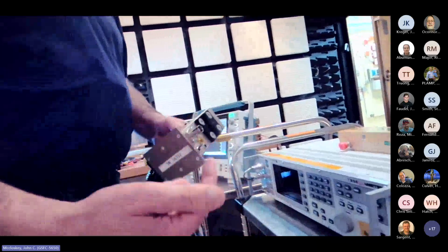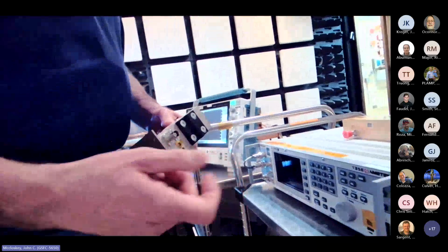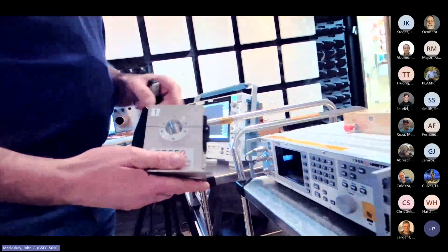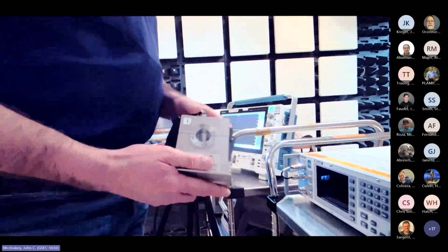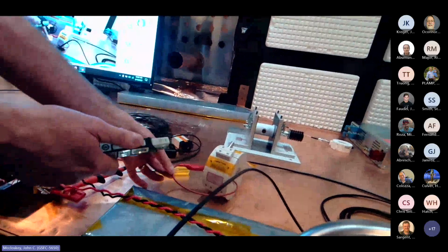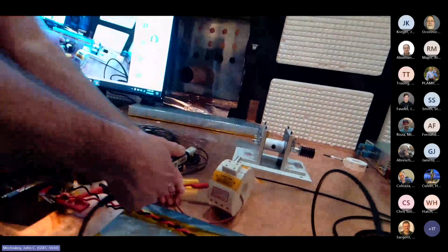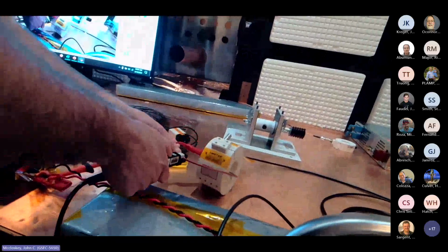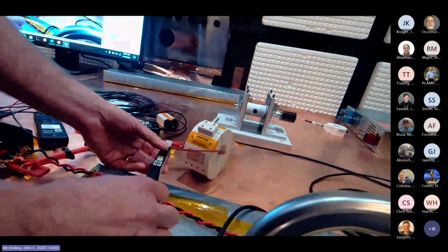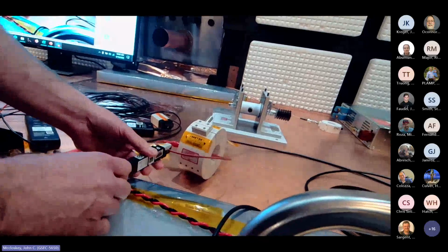Because it's only going to measure the voltage that is coming out of the output connector and through the cable. So that's all part of what you have to upload into the system, to make sure that you're translating that measured voltage into the current that caused it. For this demonstration, my cable simulator is just a single wire and I can fit a scope current probe around it, so we can see the current readily without that translation. So I'm putting the current probe on here, and we're going to play back those levels into a short circuit and see what we get.